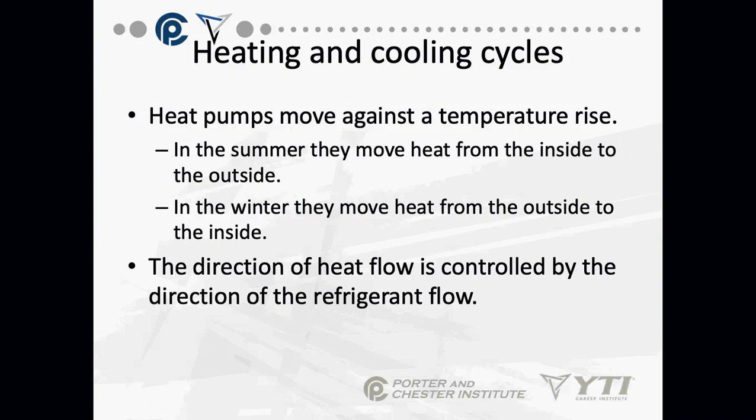The direction of heat flow is controlled by the direction of refrigerant flow. Now, let me make this very, very clear. We do not reverse the direction of the compressor. The compressor always runs in the same direction. We just reverse the flow of refrigerant after it comes out of the compressor.